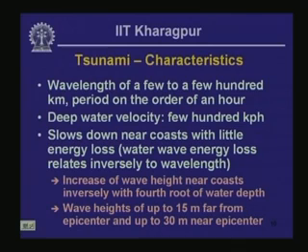So the water column is going to pile up to make up for the loss of kinetic energy, and in the process the wave height is going to increase near the coast. Simple calculations show that the wave height increases with the decrease in water depth, in proportion to the fourth root of water depth as you approach the coastline.